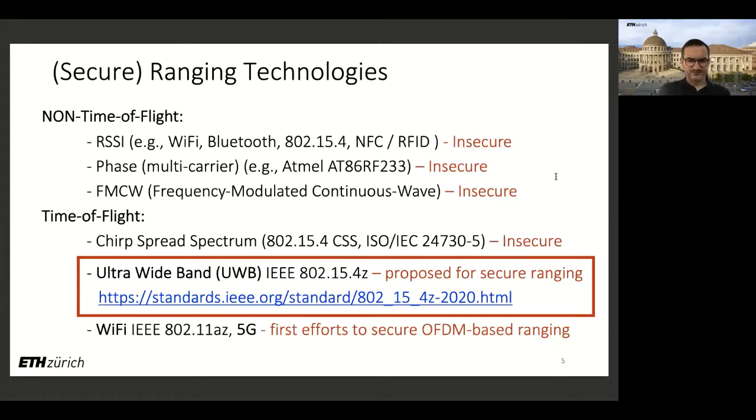Ultra-wideband is not the only technology that is being standardized for secure ranging. There are now efforts also within 802.11az, and also within 5G to achieve secure ranging. So I expect more to be done in this space.